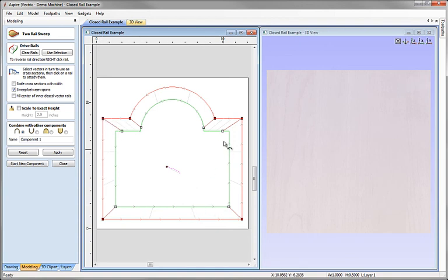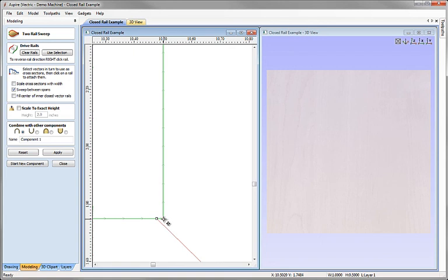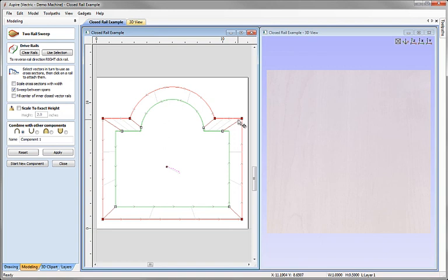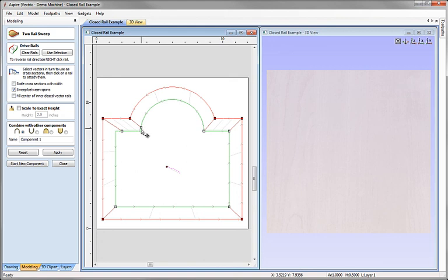Now you'll notice that these don't necessarily correspond to the points on the inside, and that is because the software doesn't know that there's necessarily a pair to the point that you're putting it at there. So what you do need to do is zoom in on these and manually click and drag to make sure that they're snapped onto the opposite nodes. I can hit F on the keyboard to fit that back into the window. I can zoom in here, click and drag that, and it'll snap, and I'll get the crosshairs showing that it's snapping. And so I can manually add these across these nodes, even though we don't have the same number between the two rails. Click and drag, you can see that snap there, I get the crosshair.